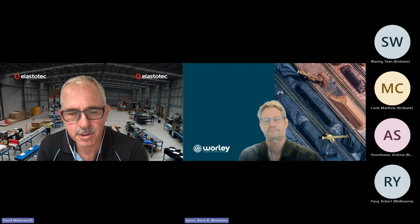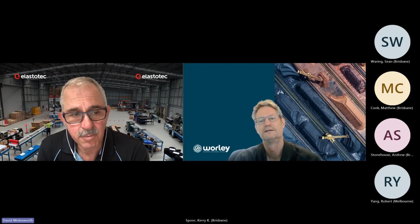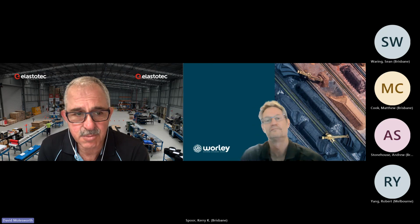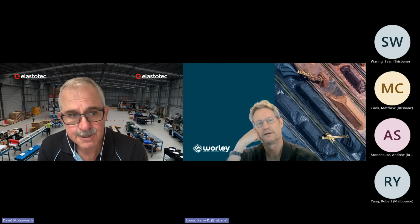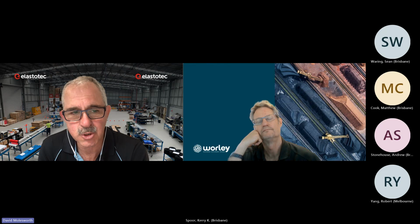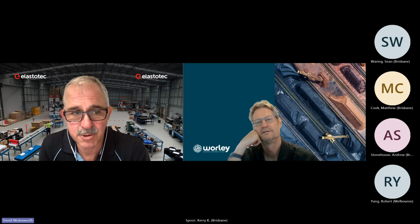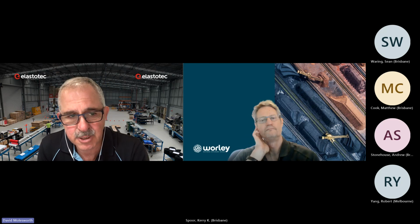Well, that example that I showed you, Kerry, was a mine in Peru, and that was the first high tension bend pulley we did, and we put hot vulcanized ceramic on it that we thought should be fine. This was before we had Lagging Select or anything like that. And that belt was down, the cords were running on the pulley in the center. The lagging lasted 6 months, but it just got torn to pieces. It's the shear stress when you get those high.